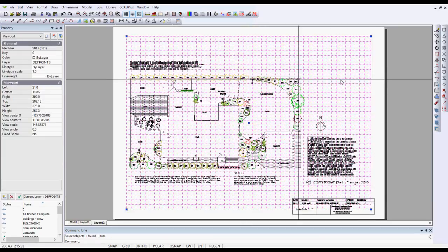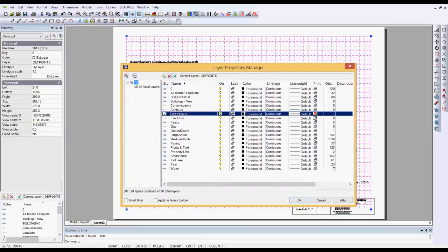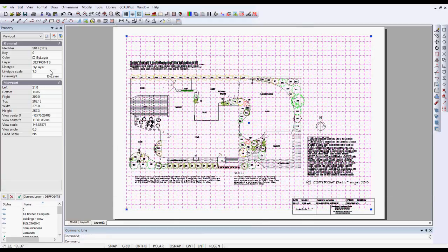All we need to do is put that on some other layer that prints, or go to our layer stack and say, no, def points is now a printing layer. But I'd recommend you keep it as it is, because AutoCAD users all use def points for anything on a non-printing layer. They might have notes about the developing design, or all sorts of useful things can be put on the def points layer. So we'll OK that, and what we'll do is move that back onto layer 0.